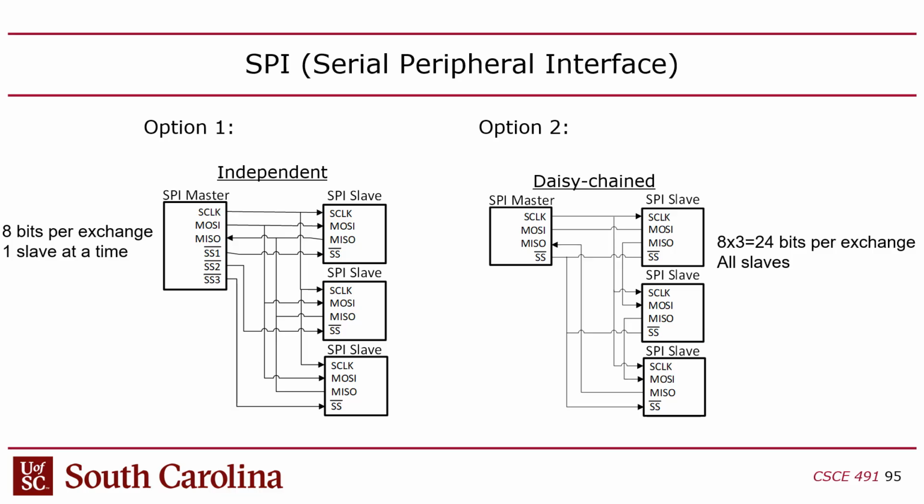They'd turn off their MISO. And hopefully there's no misunderstandings, and hopefully there's only one slave select on at a time, because it would be very easy to cause some problems if the master just activated 2 slave selects and then multiple slaves activated their MISO, which would put the MISO in contention.